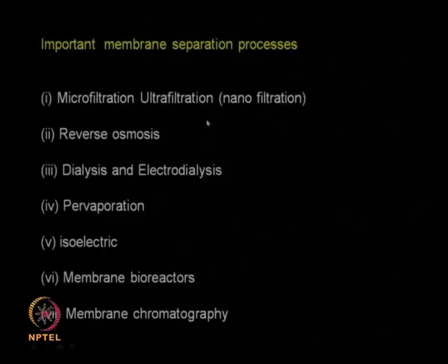in the early stages, whereas if you look at the filtrations like micro and ultrafiltration, it is well established, reverse osmosis is also well established, dialysis, electrodialysis is also well established, pervaporation is also well established. Isoelectric focusing is more in the lab scale. Membrane bioreactors are already in the market at a commercial scale.